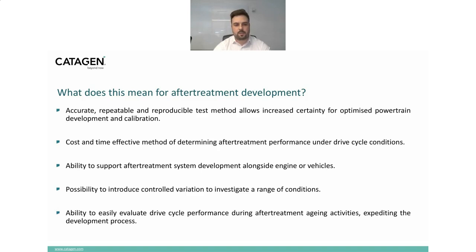Other areas where this could be useful might be in PGM optimization, where we can effectively evaluate catalyst performance, not just in terms of light-off and OSC, but also in terms of drive cycle performance and how that changes throughout the course of aftertreatment system aging.